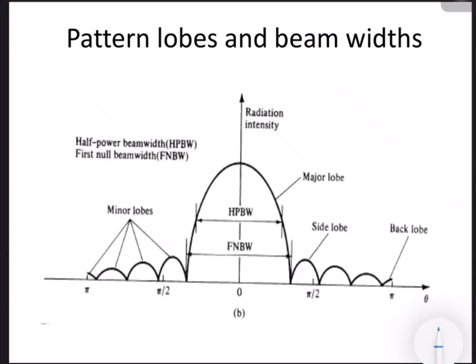The radiation pattern is a very important parameter for an antenna, because whenever an antenna radiates, the radiation pattern analysis can be done, which leads to the calculation of the half power beamwidth. And by knowing the value of half power beamwidth, we can calculate the directivity and gain of an antenna. That's why the radiation pattern of an antenna is a very important basic parameter.